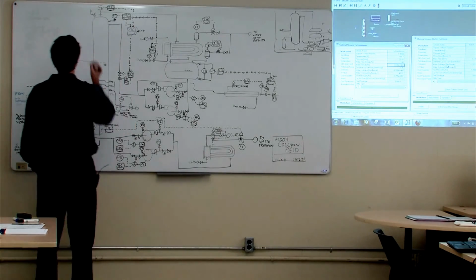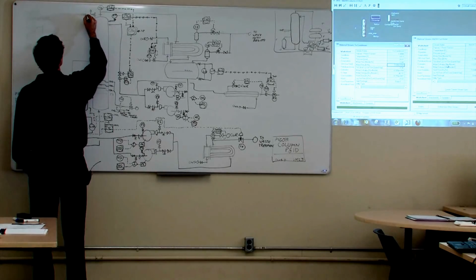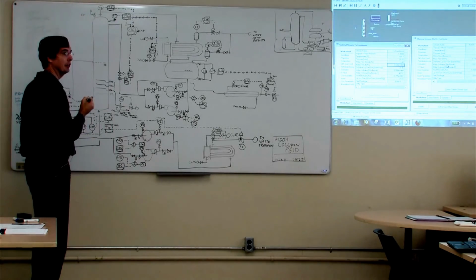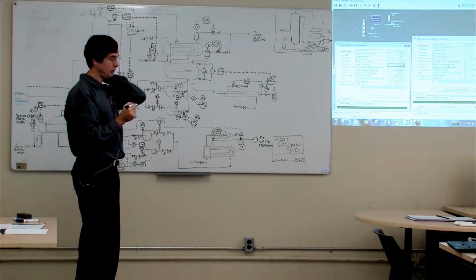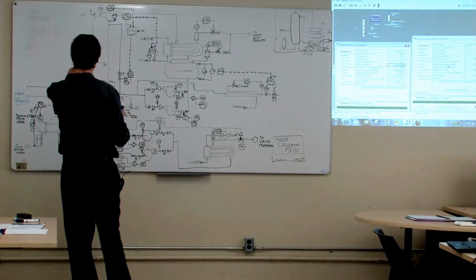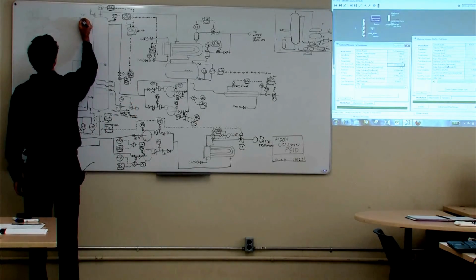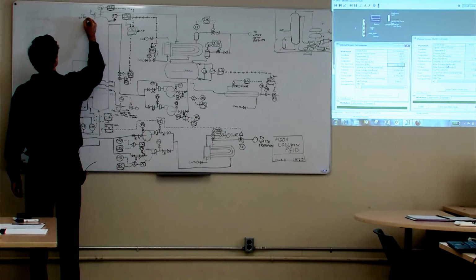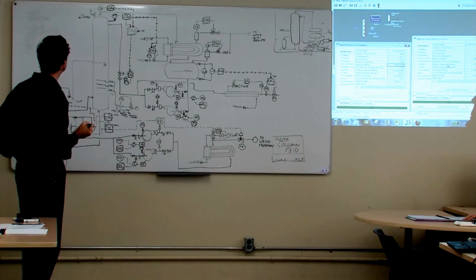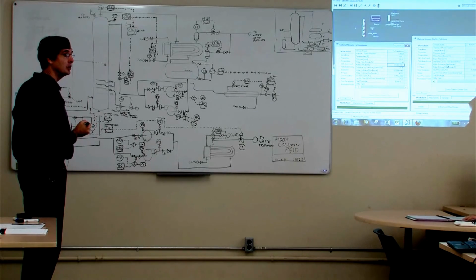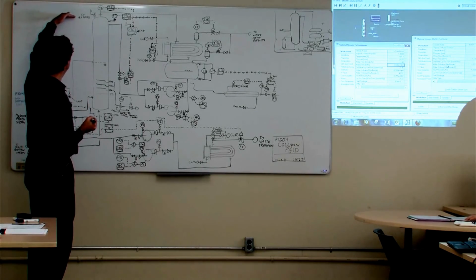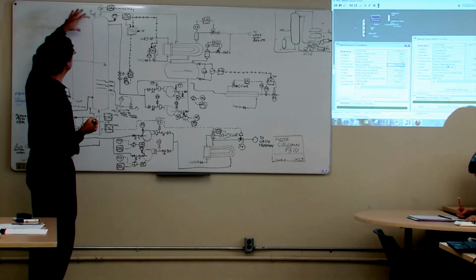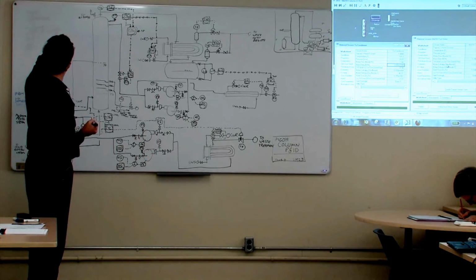So that relief valve is going to have a set pressure. What's your design pressure for the column, you guys? 2.5 bar. Can't be 2 bar. Set at 2.5 bar gauge. Okay, that's pretty close to the operating pressure. I'd almost be tempted to push it higher than that, to get it further away from the actual operating pressure.